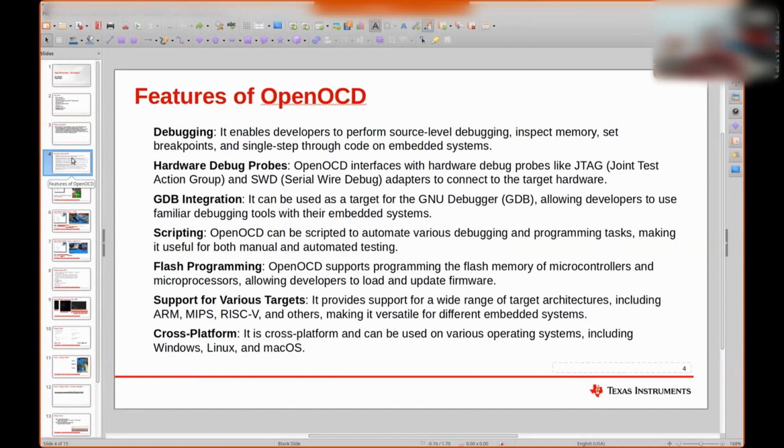CCS gives you tracing capability, some of the configuration files and GEL files that we usually create, right? That kind of support, which is essentially DSS scripting capability. On top of that, positioning would be what we would call high-end debug tools like Lauterbach, etc. So long story short, OpenOCD is your entry-level debug tool.